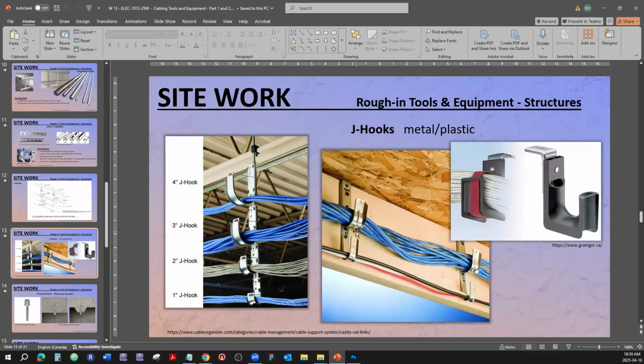They change the specifications of the cable to the point that the cable might not be certifiable as Cat6, Cat6A, Cat7, or whatnot. So 4 feet apart, and quite often that is actually mentioned in the contract, that the J-hooks should be no further than 4 feet apart.